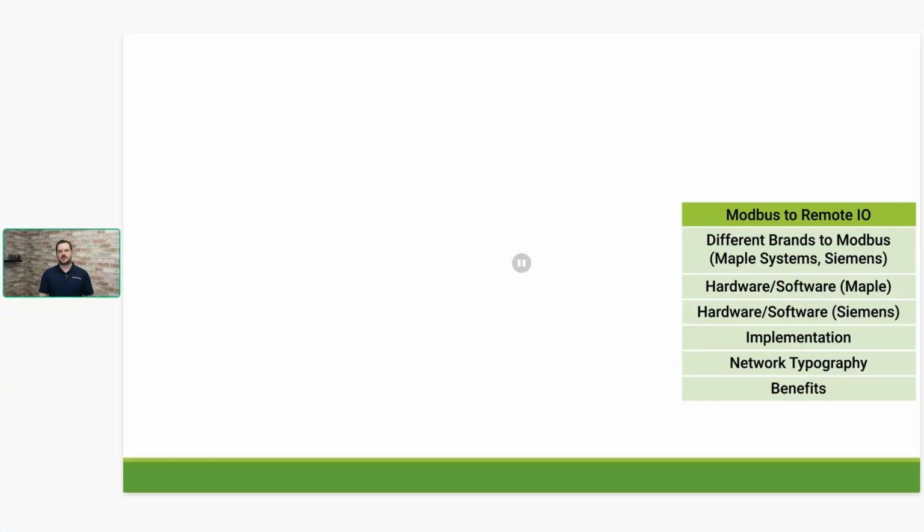So to keep that closer to the remote I/O. If your PLC is in one section of the building, you don't want to run hundreds of feet of wire because, again, that's just not going to be ideal for an accurate reading. Next question that I have here is, is there a limit to how many remote I/O couplers you can have?